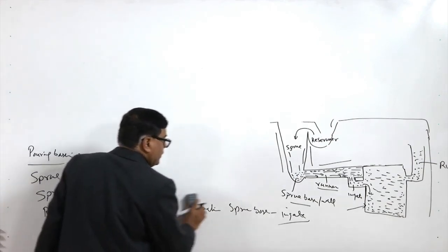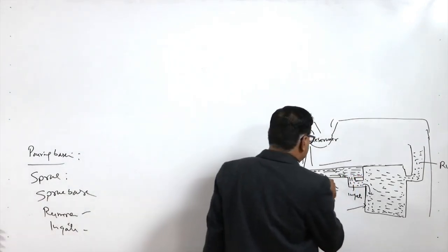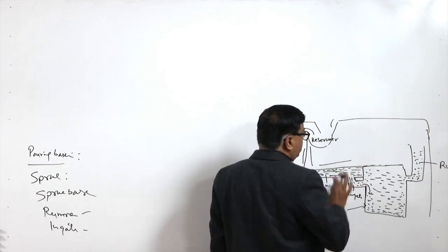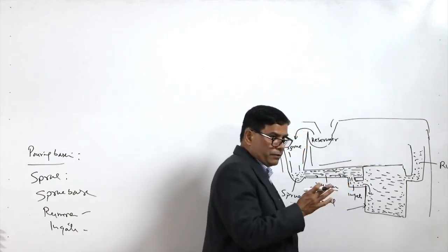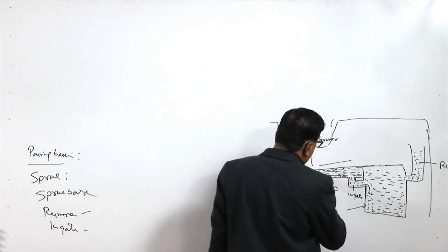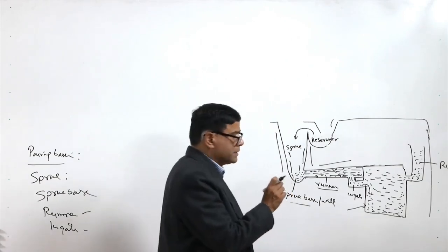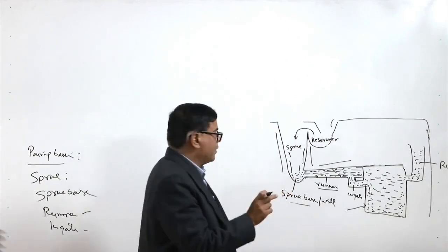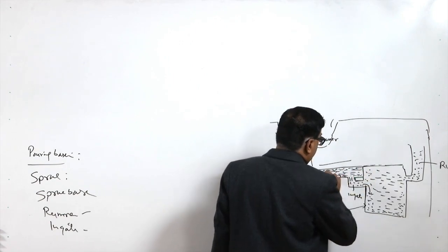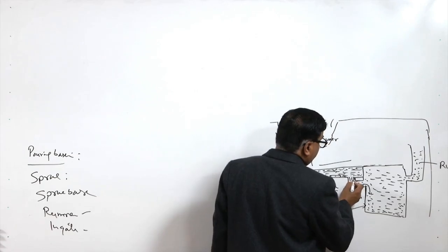Here one typical feature is that it is always desired that the runner is always full of the molten metal, so that no negative pressure zone is created. Still, even when it is full, the lighter, low density material like impurities, slag, dross, sand, etc., will be floating over the top layer, while the molten metal is fed from the bottom.